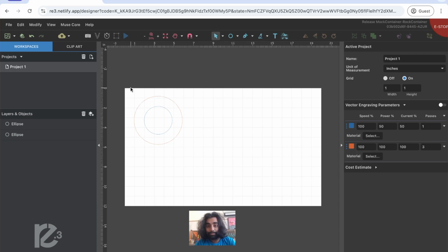So, to recap, cutting and etching is a vector path-driven process where truly the only difference between them is the strength of the power and current level. The shapes you create with them, the entities you create, the graphics themselves, are practically the same. So, now that we understand all this, let's go ahead and send this out to the laser cutter and see what it looks like in real life.